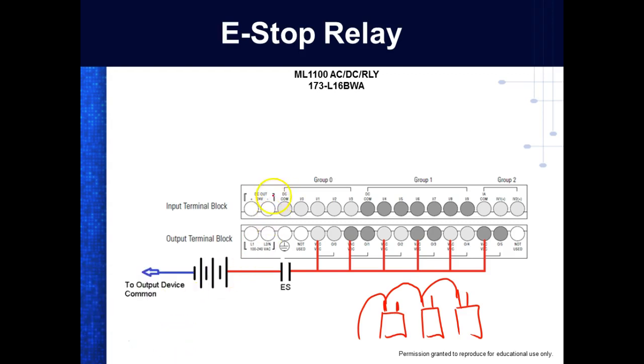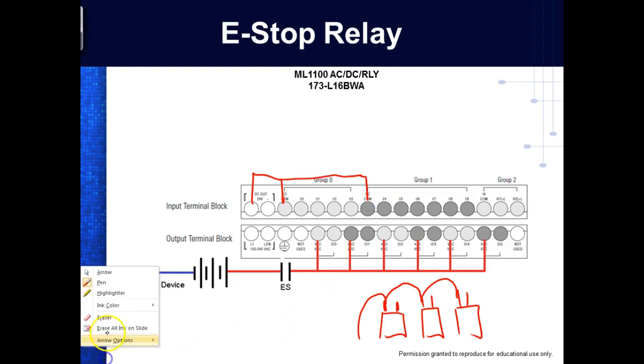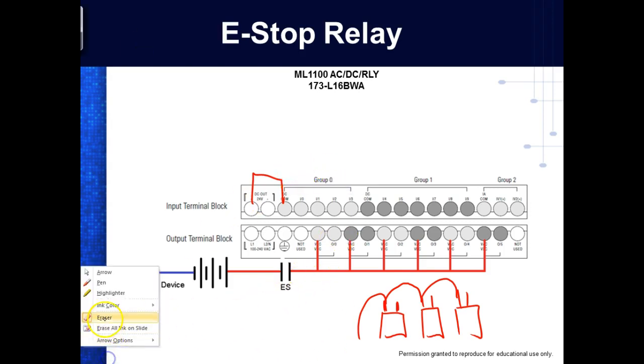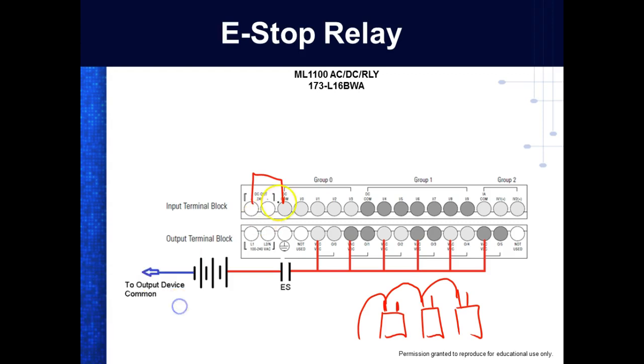And then what I'm going to do is take this plus and run it to that common, and run it to that common right there. Or I could set one of them for sourcing and set the other one for syncing, right? You understand that? So I could come over here and set this one for sourcing, and then I could come over here and set this one up for what? Syncing, which is pretty neat.